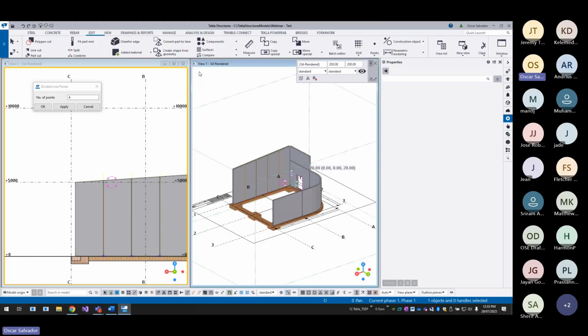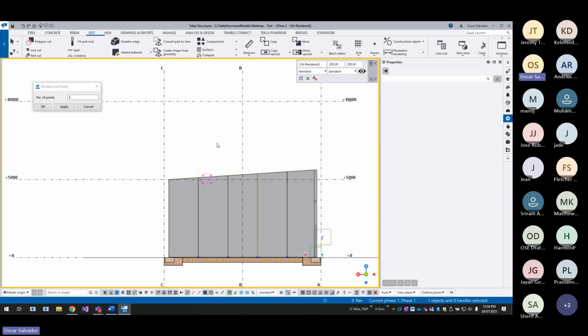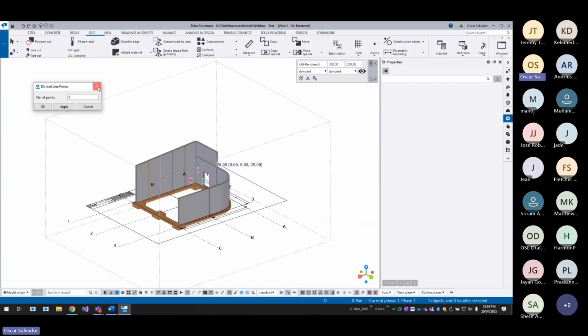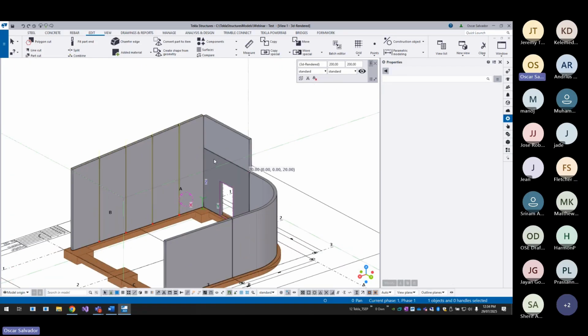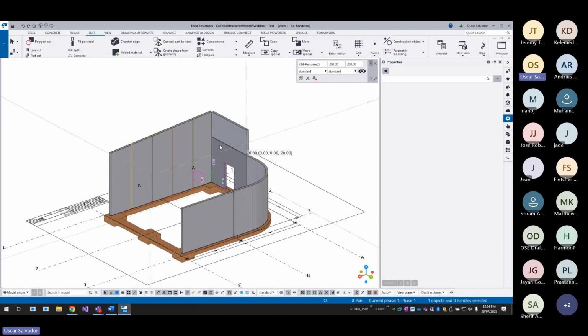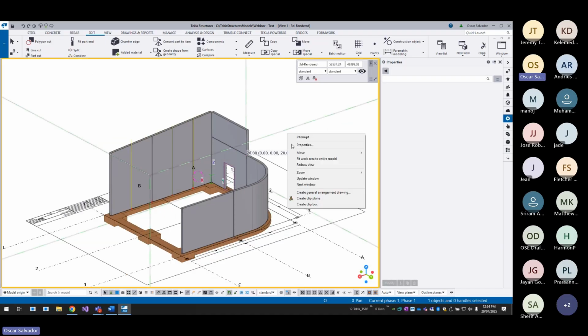Okay, so let's set this view aside for the meantime, and let's go back to the 3D view. Before doing connections again, another thing is to check the panel form face. This determines the front face and the table face of the panel, and it needs to be corrected before creating the connections and the drawing.